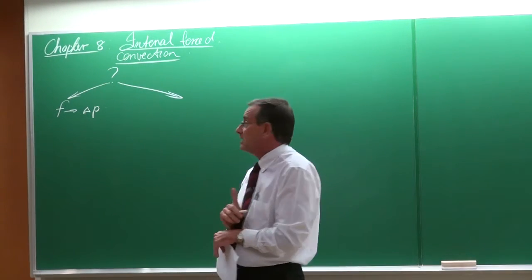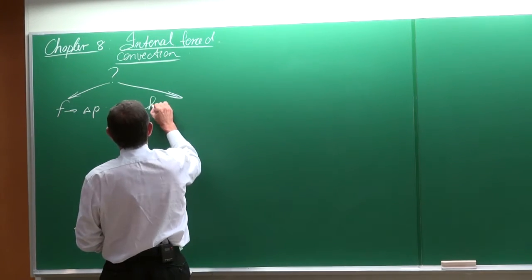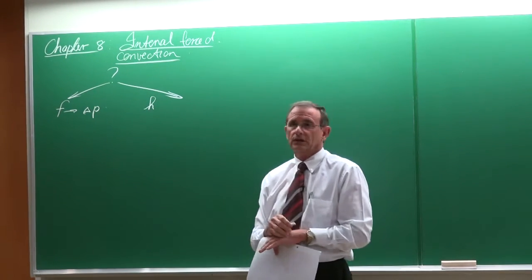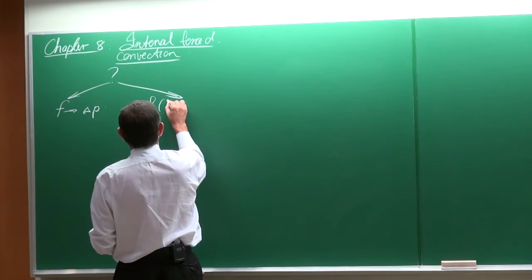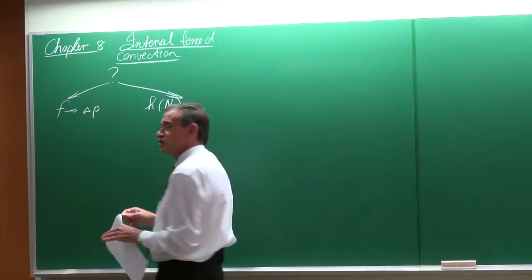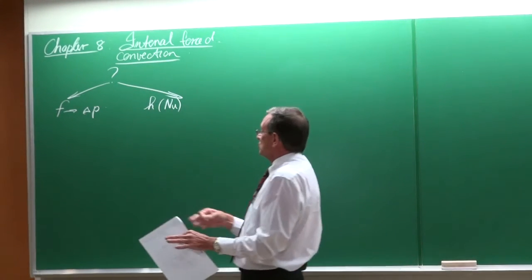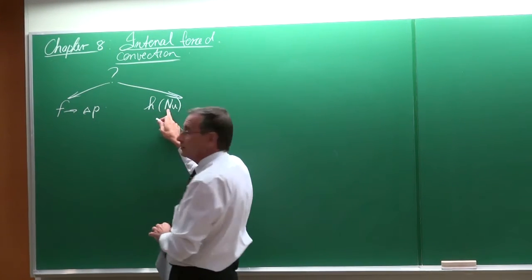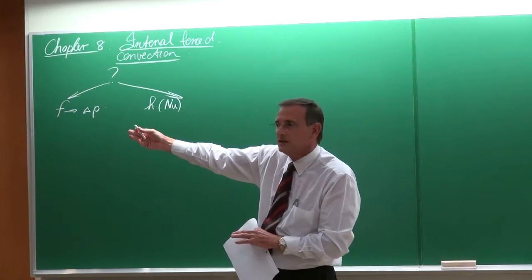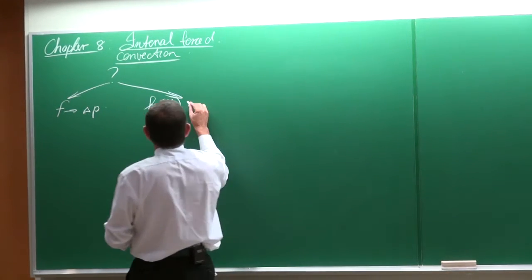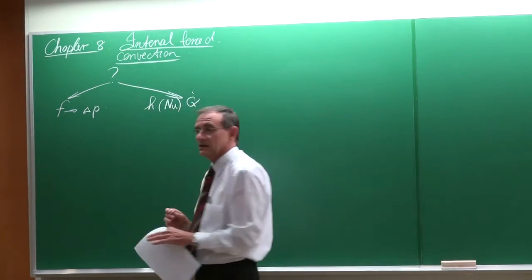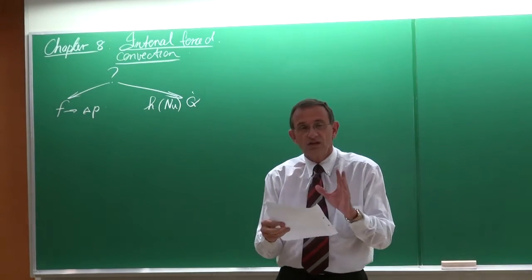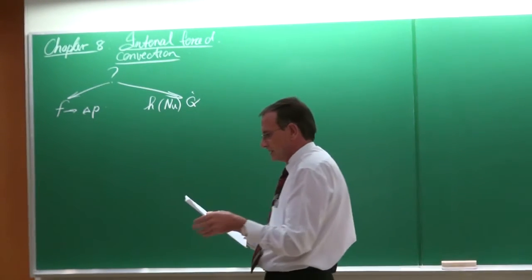And then the second thing is we want to obtain the heat transfer coefficient. And it might be from a Nusselt number, which is the non-dimensionalized heat transfer coefficient, just like this friction factor is a non-dimensionalized one. Normally we want the Nusselt number so that we can get the heat transfer coefficient, and when we get the heat transfer coefficient, then we can calculate the heat transfer rate. So those are the things that we're typically very interested in.